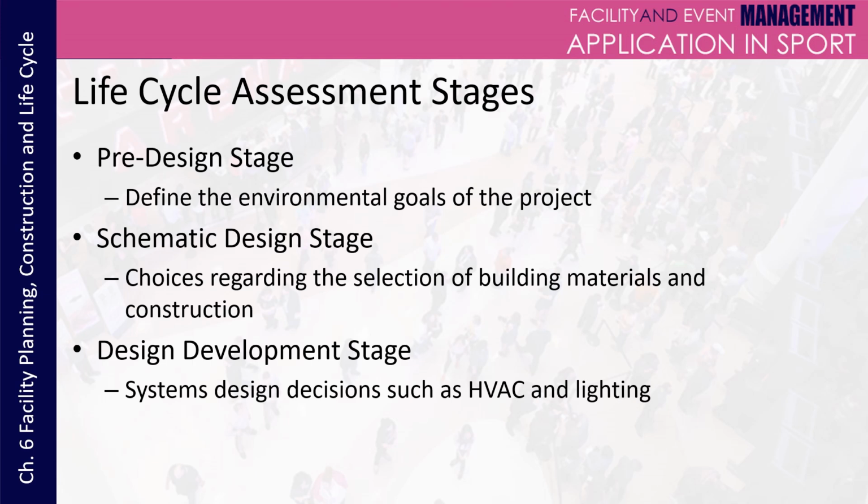And the third stage is the design development stage. Here, you're making systems design decisions, such as including HVAC, lighting, and water systems. And you're selecting energy-efficient technologies like solar panels, LED lighting, and water-saving fixtures, and optimizing the building's orientation and insulation to enhance natural lighting and ventilation. For example, installing geothermal heating to reduce reliance on fossil fuels.